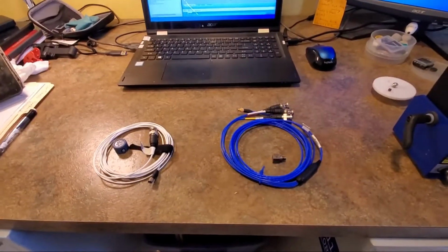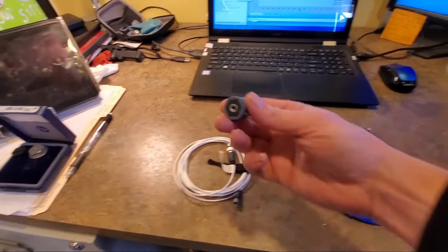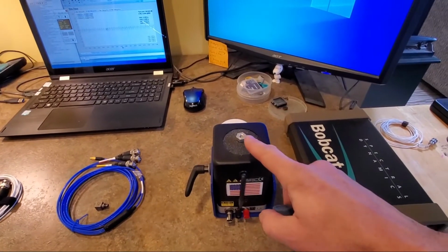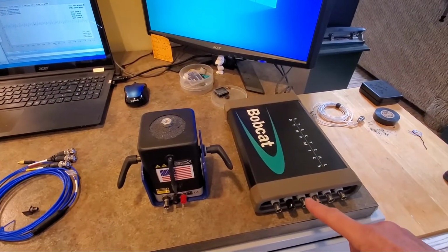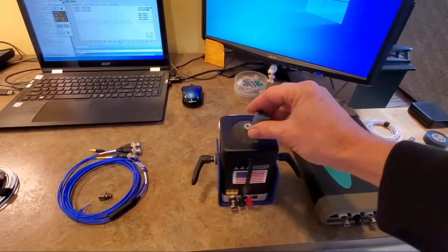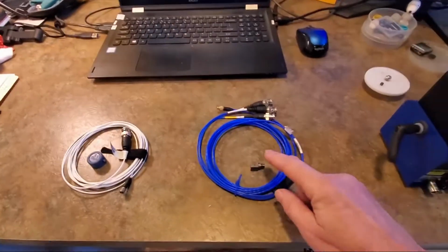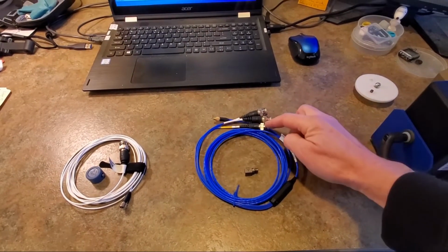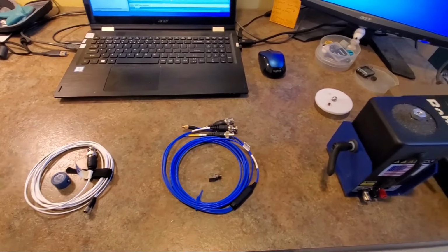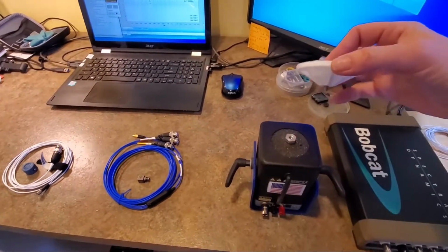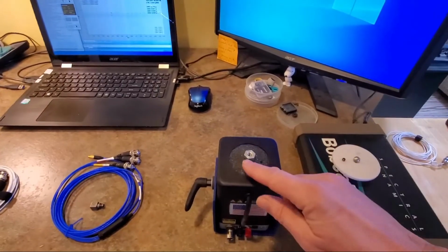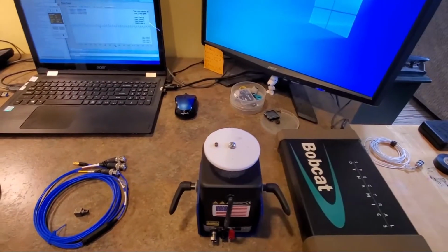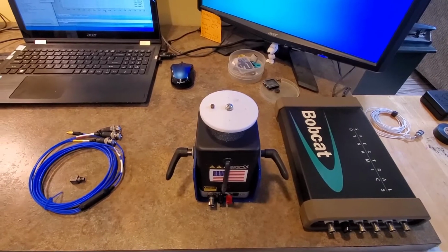Over here we have our measurement devices. This is an accelerometer. So this piece connected with a cable will go on top of the shaker, and it'll measure the motion, and it goes into the data acquisition system, and we can determine the amount of motion from there. There's another type of accelerometer. This one's very old. It only measures one direction. This one measures 3 directions, called a triaxial accelerometer. And this piece here is called a head expander. You can see that the head of this shaker is very small. So we put the head expander on top of the shaker, and the accelerometer will be mounted on top of the head expander.